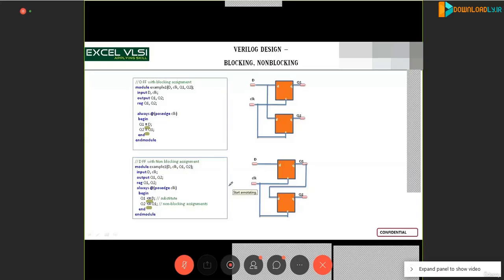then what you will realize is the D input is the same feed to both the flip-flops here. But that is not what you wanted to implement. You wanted the first flip-flop output to come to the second flip-flop input. Of course both the clocks are connected to the single clock source. But with this mere way of coding, you see a different hardware implementation.